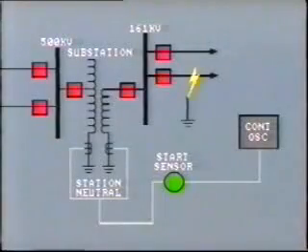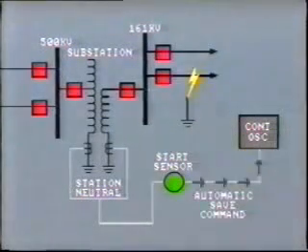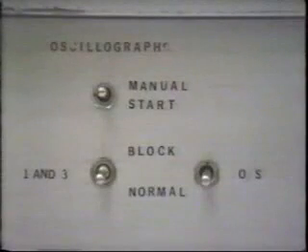When a fault occurs, we can save about 6 hours of data by initiating a save command. This can be done automatically by protective relays or other sensors immediately after a fault is detected. Data can also be saved manually by a remote switch on the operator's console. Since data is continuously being recorded, the operator can decide to save information after the disturbance has occurred. Once the data is saved on magnetic tape, we can get a hard copy printout of the waveforms for analysis.